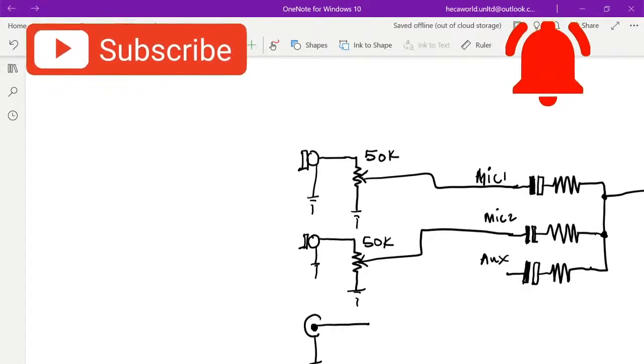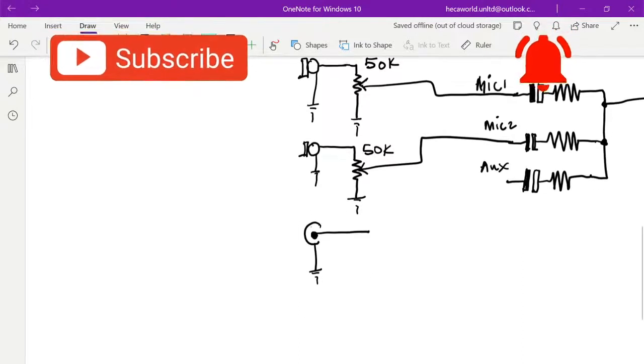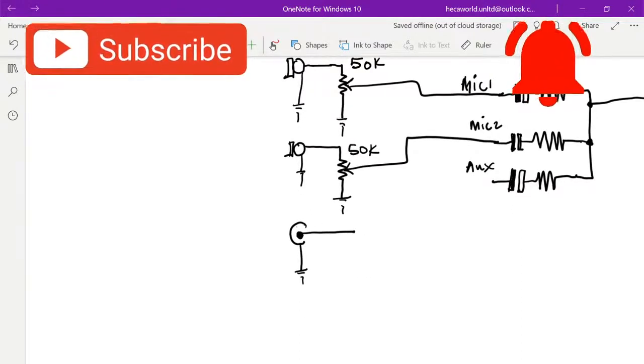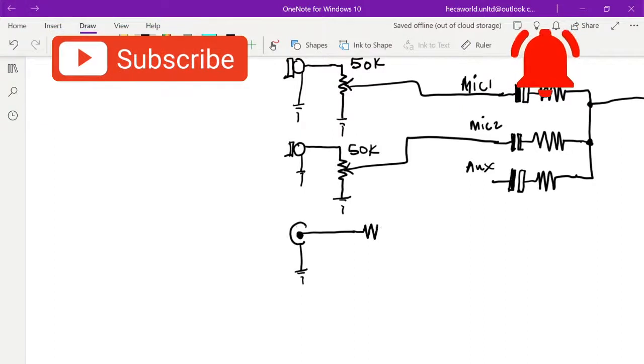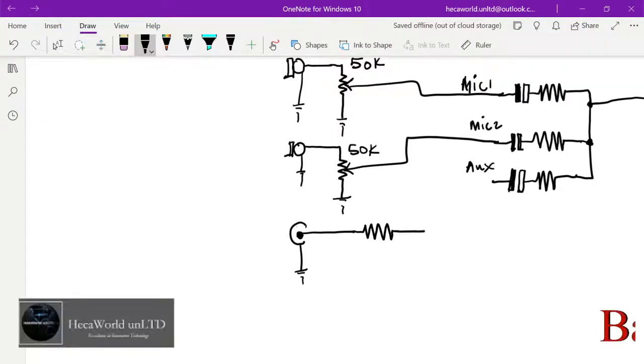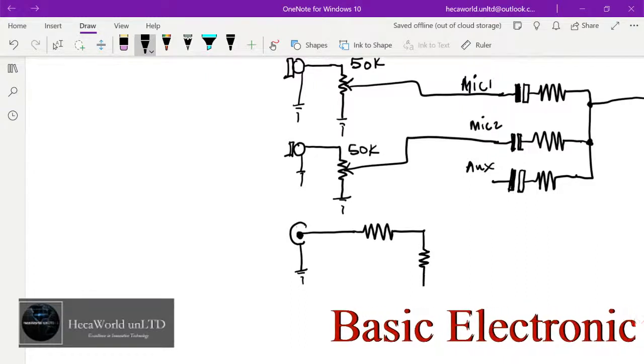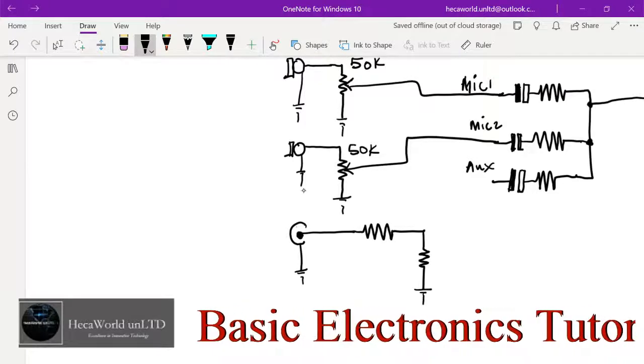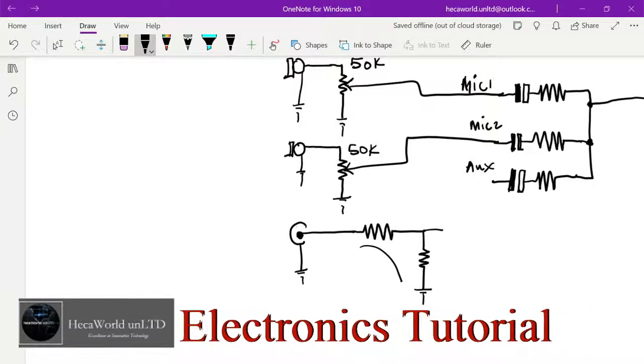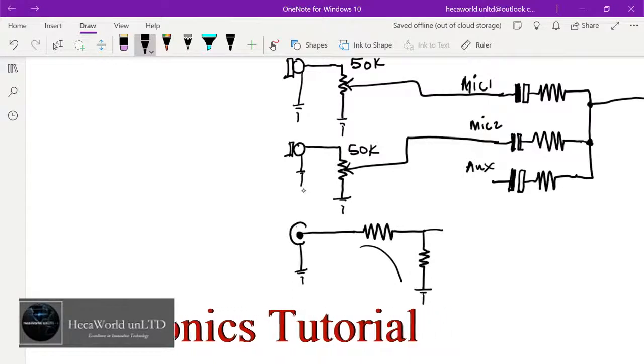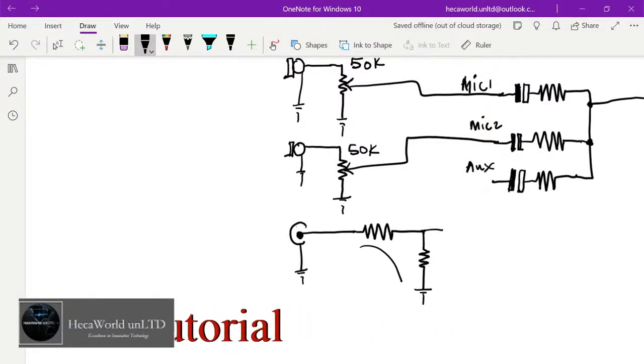So what you're going to do is, you remember our discussions on resistors as voltage dividers. So you're going to build a voltage divider around here, and this is going to be an attenuator, not an RF signal attenuator, but an audio signal attenuator. As you know, these two resistors are in series. If you have nothing connected in parallel at this point, the same current will flow through them. So voltage dropped here and voltage dropped here will be proportionate to the value of the resistance, right?